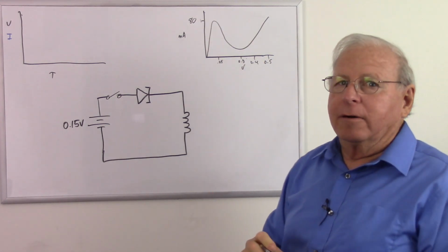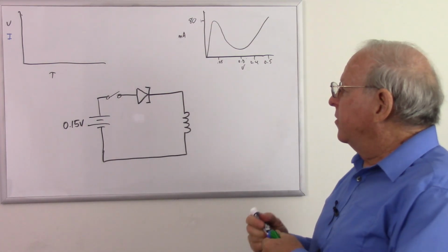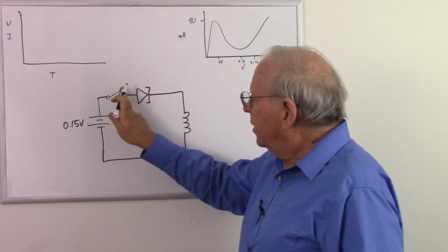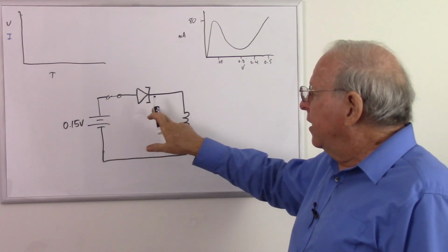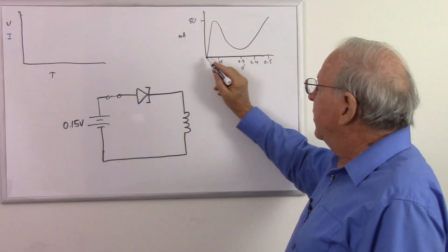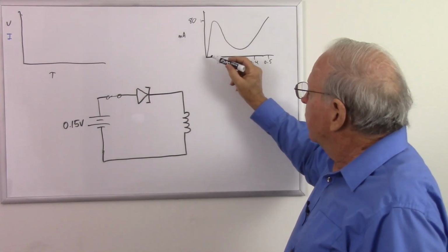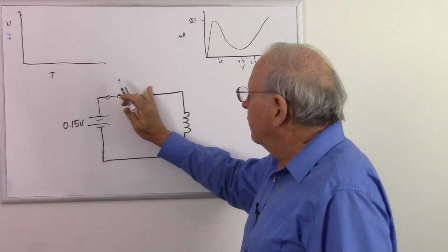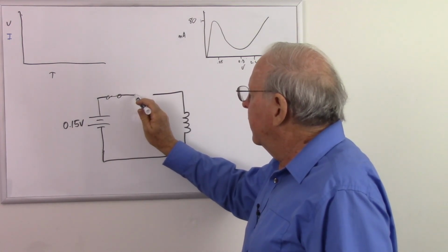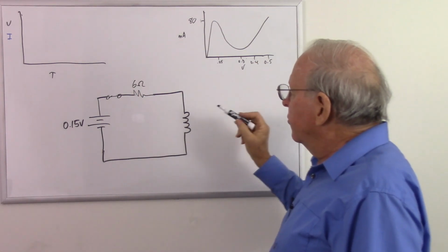All right, here we go. Take a breath. Let's flip that switch and see what this is going to do. So we flip the switch, and at this point, what's that diode look like? We've just flipped the switch. We have 0 volts and 0 current. We're over in this region here. And what does it look like? It looks like about a 6 ohm resistor. So let's go ahead and get rid of our diode. Just see that as about a 6 ohm resistor.